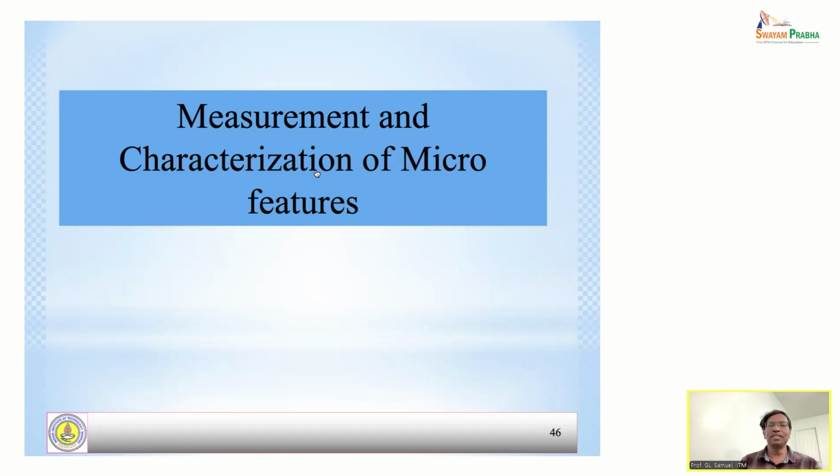And they have been changing the design of these blades, and nowadays we have different shapes of holes. They are not at 90 degrees, they are inclined, and we have oblique holes, different shaped holes. They are not all circular, they have different shapes. We have been working with GTRE in Bangalore, the Gas Turbine Research Establishment, where we are trying to see how we can produce the holes and make them more efficient.